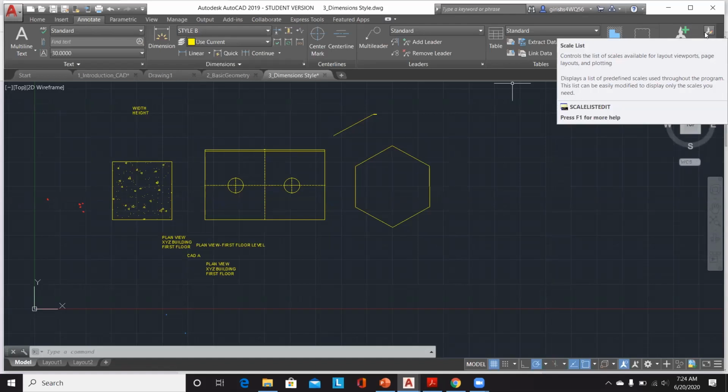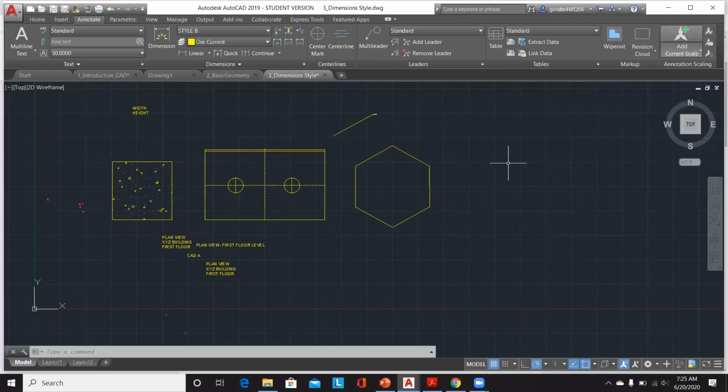If you're using a metric system of drawings, you can use either 1:1, 2:1, or 100:1 based on the way you configure your drawings. And you can create a scale list that will help you manage the way the scale appears in the drawing space. We will discuss this in detail in our next subtopic for the day, which is how to add layouts and how to control our drawings in the layout window.